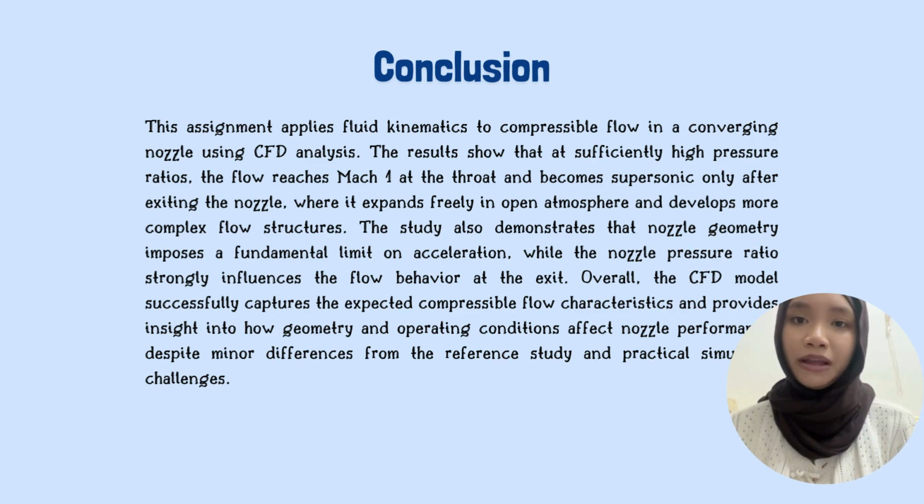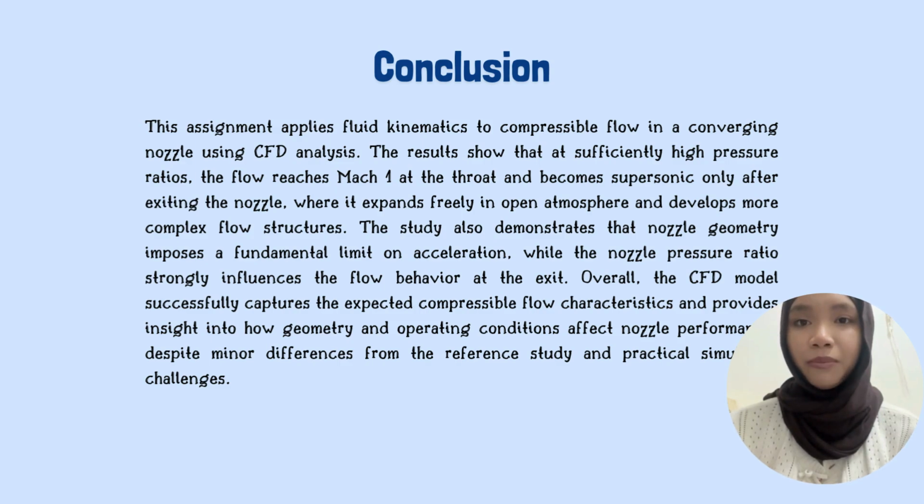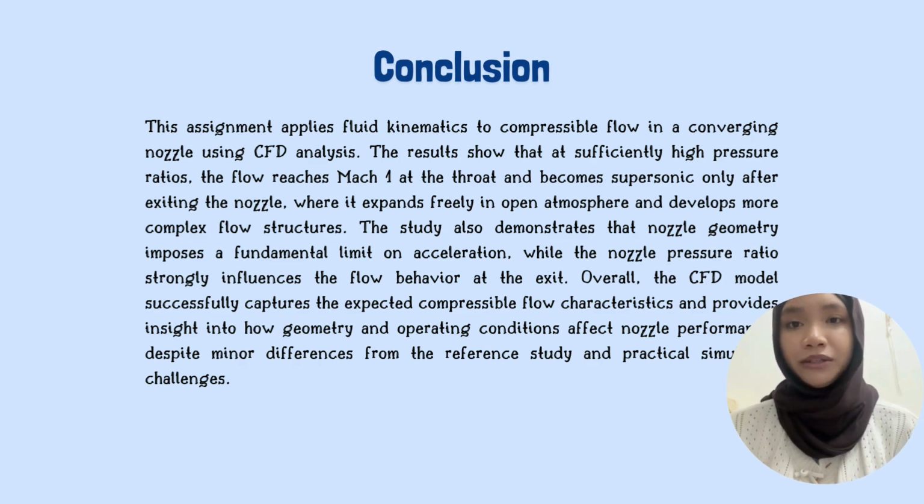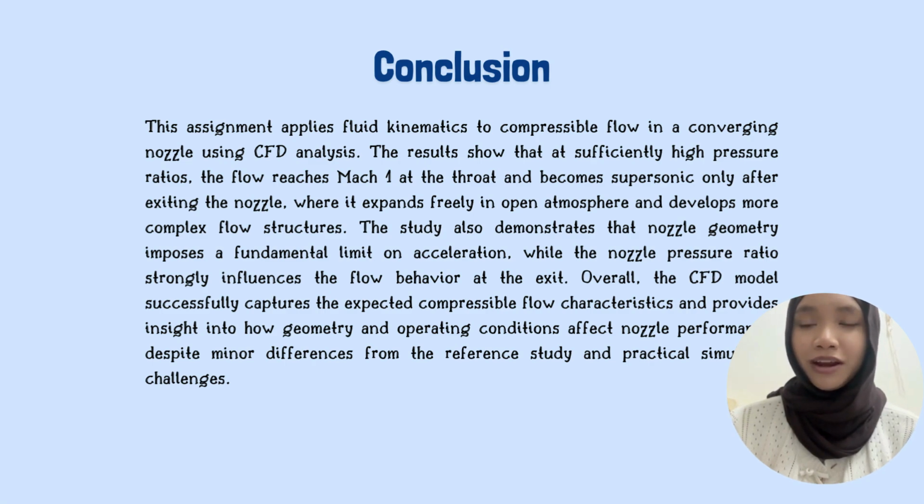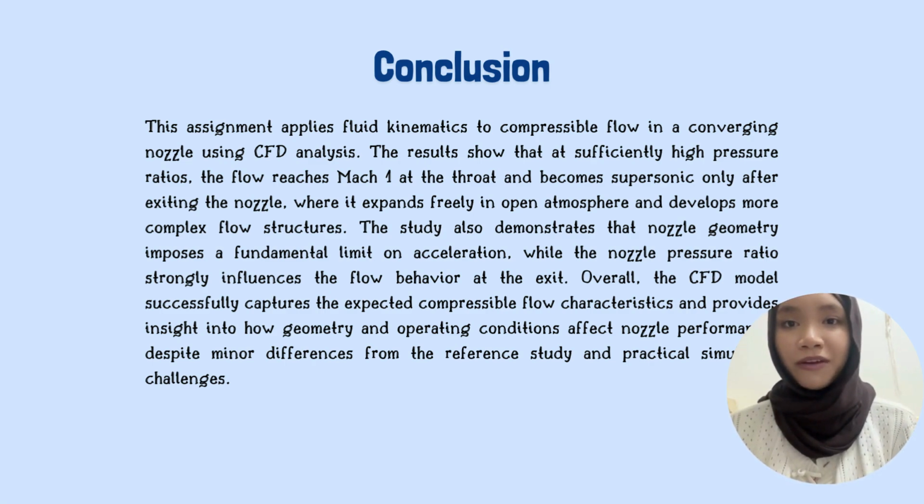At higher NPR values, strong pressure differences lead to more complex flow structures and alternating expansion and compression patterns downstream. Overall, the CFD model developed in this study successfully captures the expected flow behavior and provided a good understanding of geometry constraints in compressible flow. Although there are slight differences compared to the reference paper, this study offers valuable insight into nozzle aerodynamics as well as the practical challenges of CFD simulations, including meshing difficulties, computational limitations, and long simulation times.